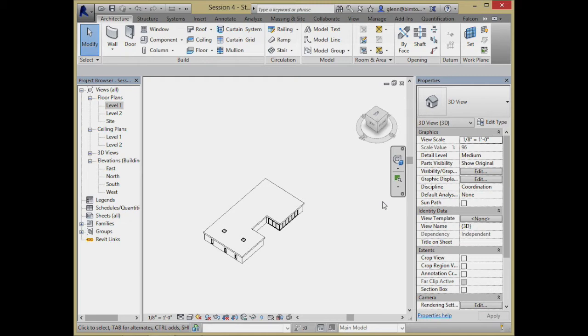Because of this building, yes? The corners of my curtain walls don't meet. Is that gap going to be affected in Ecotect? It would affect it from a thermal standpoint, so we'd have a gap. Let's see if we can stretch them and bring them together. Take a look and see if you can make them join up. You might have to trim them, or sometimes I pull them apart from each other and bring them back together again. It's one of those sorts of things.